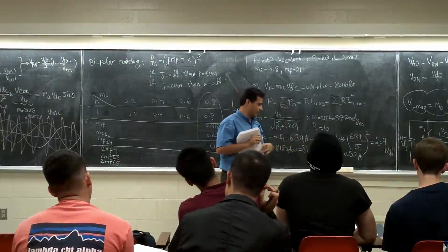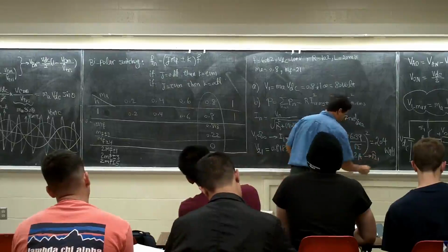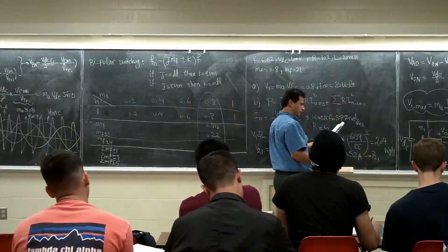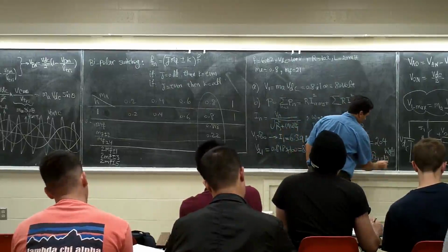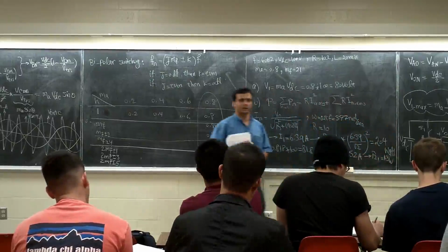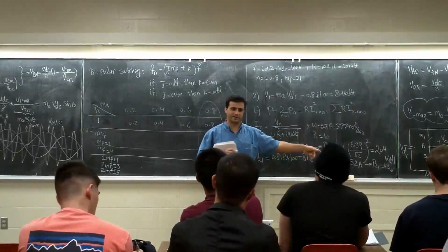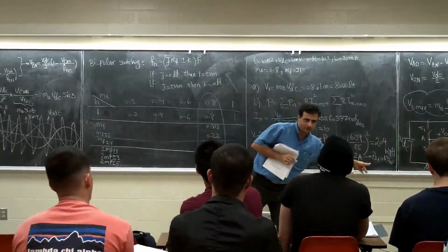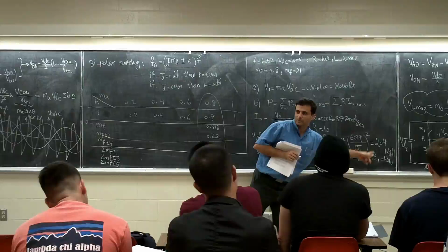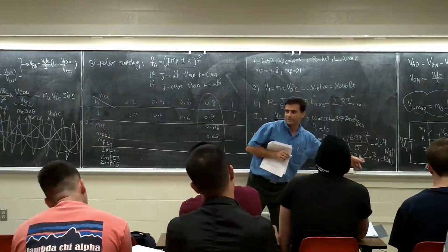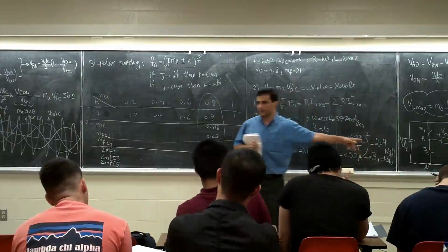And you can calculate the power for this one, P21. It is going to be 1.31. This is the big guy among all those bad guys. How much is it? 1.3 watt. How much is this one? 200 watts. It's 0.5%. That's the reason I'm saying we don't care about the rest of the harmonics. The first one is going to give us that.